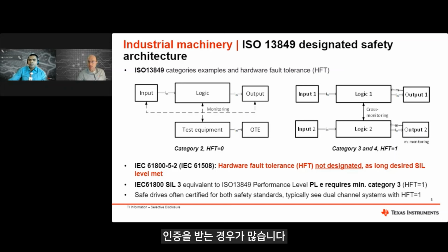What about excessive temperatures? Safety limiting values are specified in the datasheet. Here, the example from the UCC21750 datasheet. We see maximum current and maximum power. They intend to minimize potential damage to the isolation barrier upon failure of the input or output circuitry. A failure of the I/O can allow low resistance to ground or supply and, without current limiting, dissipate sufficient power to overheat the die and may damage the isolation barrier. To prevent this, a possible system solution can use an LDO with a current limit, or it can use current limit resistors, as shown in the right-hand figure. For more information, refer to the application note, Understanding Failure Modes in Isolators.